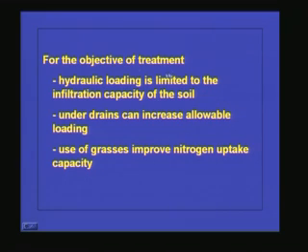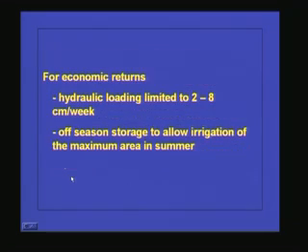And for the objectives of treatment, the hydraulic loading is very, very important, and it is limited to the infiltration capacity of the soil. If the hydraulic loading is more than the infiltration capacity, water stagnation will take place. Underdrains can increase the allowable loads, because water is percolating through the soil. If we can collect it and pump it up, then the loading can be increased. Use of grasses improves the nitrogen uptake capacity.